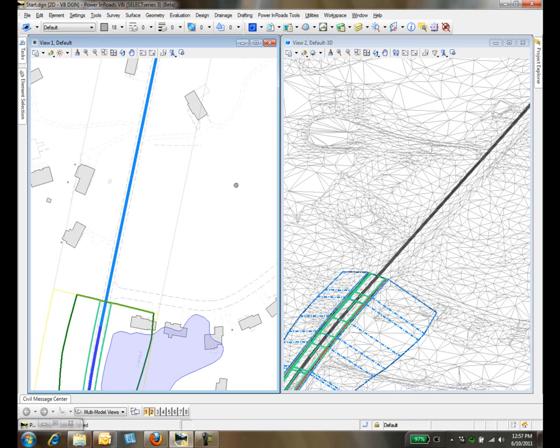Now let's take a look at a few things that we have available to us. You'll notice in the 2D view here that you've got this gray outline. This actually represents our corridor, and what it does is give us the ability to graphically select our corridor. When I do that, just as we did earlier, we get our context toolbar. So you can see the consistency in the user experience or the interface. It doesn't matter whether it's a terrain model, horizontal or vertical geometry, or even our corridor. When you select it, you will get the same context toolbars.